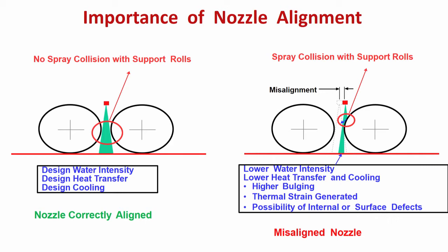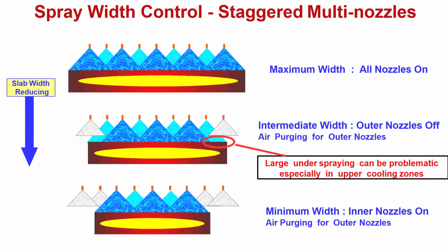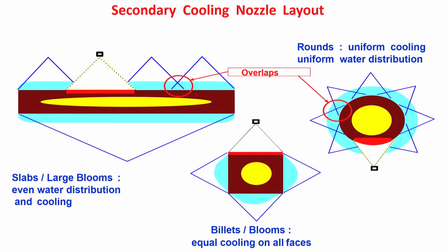Earlier I talked about, you remember, non-functioning of a nozzle. This nozzle was not functioning. So, that was creating non-uniformity, non-uniform temperature distribution, possibility of reheating, possibility of shape change because of stress generation. So, that was one problem. The nozzle location was there, okay, but it was not functioning. So, a non-functional nozzle created non-uniform cooling.